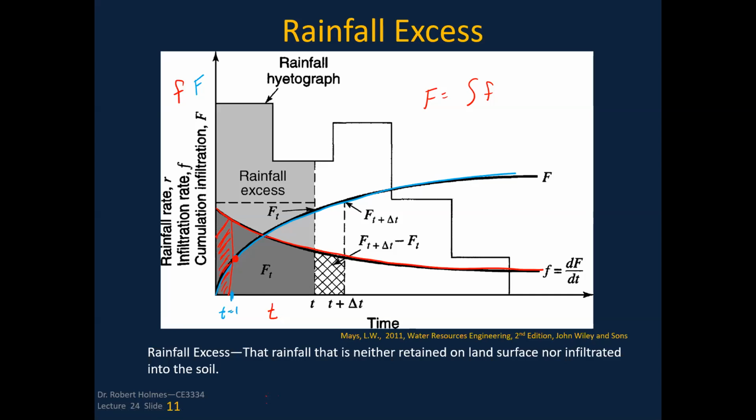And so, kind of an important point to make. If I go along here and I say, okay, I want to know what the cumulative infiltration is all the way over to this time, well, I just take the total area underneath that, and that's equal to this value right here. So this is my total cumulative infiltration. This is an infiltration rate.